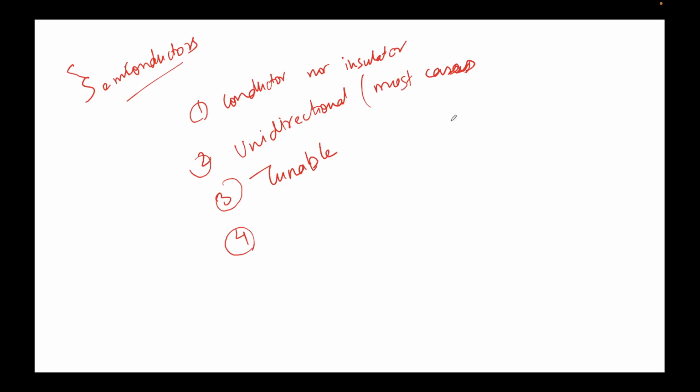For instance, if I have a copper cable, and let's say I know the resistance of this copper cable is 10 ohms, and I want to drive a current of 1 amp through this. So I can always apply 10 volts here. However, if I want a current of 10 amperes, I can always apply 100 volts here. So this is also tunable, is it not?